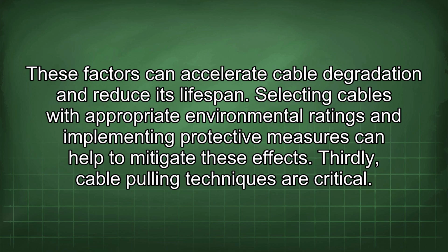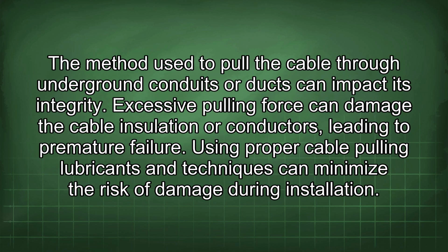Thirdly, cable pulling techniques are critical. The method used to pull the cable through underground conduits or ducts can impact its integrity. Excessive pulling force can damage the cable insulation or conductors, leading to premature failure. Using proper cable pulling lubricants and techniques can minimize the risk of damage during installation.